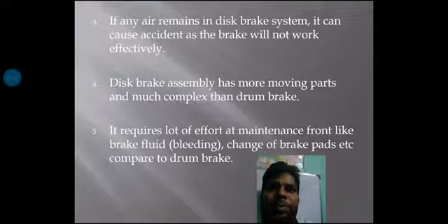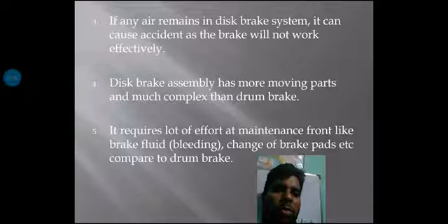But one question is there, as we apply a method similar to the clutch. Here again we can use two methods similar to clutch theory, that is uniform pressure theory and uniform wear theory.